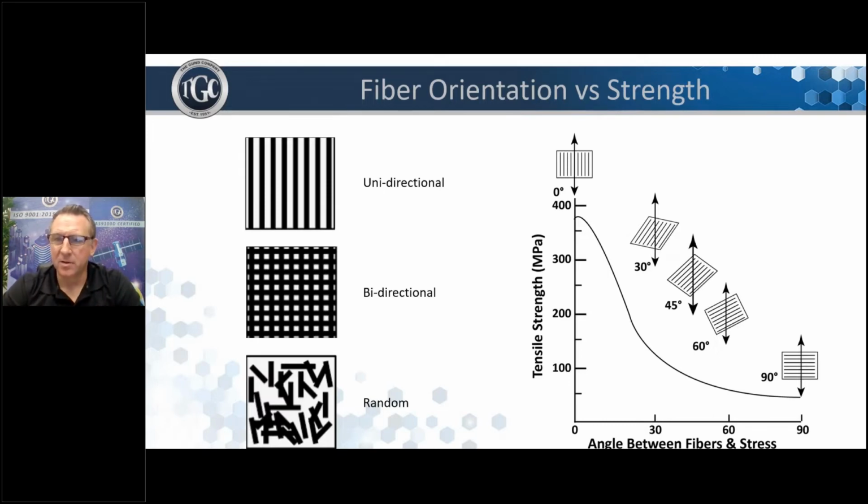Fiber orientation also has a correlation to nearly all mechanical properties. When designing, cost needs to be considered because optimizing fiber orientation usually comes at higher cost. For example, random fiber mat is very inexpensive, but quasi-isotropic fabrics that provide fiber placed in 0, 90, plus 45, minus 45 orientations are very expensive, but the properties obtained by using them are nearly isotropic.